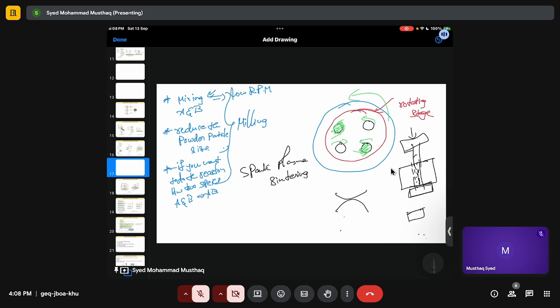In this pellet, the powder particles are touching each other, which is obvious, and then you apply current. Whenever the current flows inside the powder particle, it is okay, but when it is crossing the path between particles, you have a resistance, which you can call contact resistance. And whenever you have a resistance, I hope everyone remembers, Joule's heating.